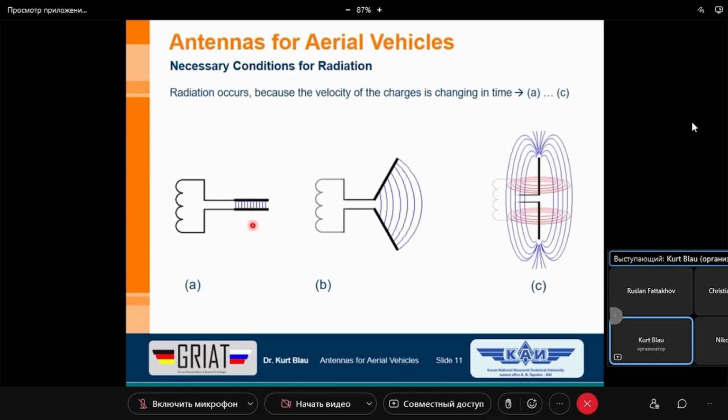The capacitor is charged. And in case of, let's say, a dielectric material of air, the capacitor has a very, very high quality factor. The lowest quality factor is given by the inductance, as you know, because the conductivity of this material, for instance copper, is not infinite, it's finite, and this creates the losses, and so the quality factor of this parallel resonance circuit is limited. Means in this moment I connect this, then we have a very short oscillation, goes down to 0 in a very, very small time. Let's say in a few microseconds, the oscillation ends.